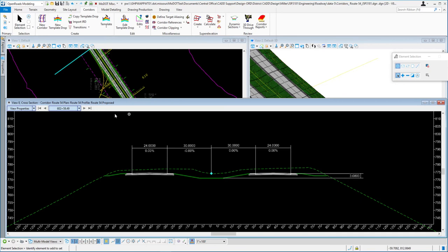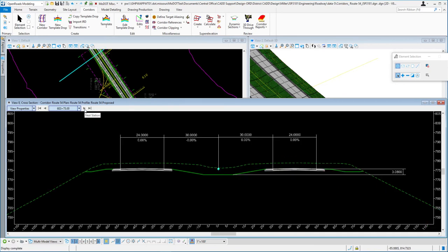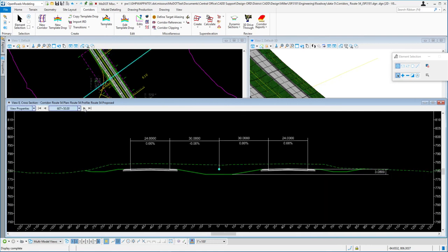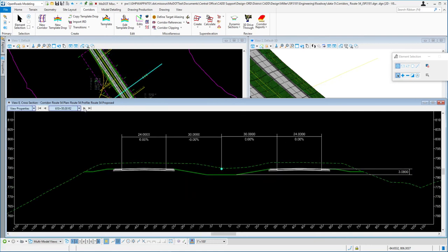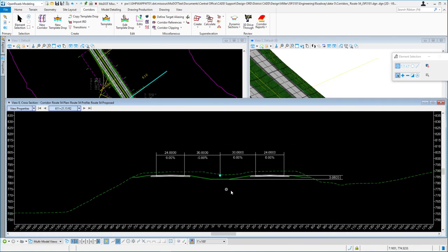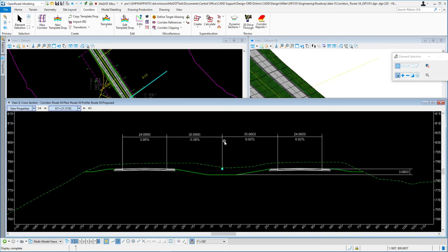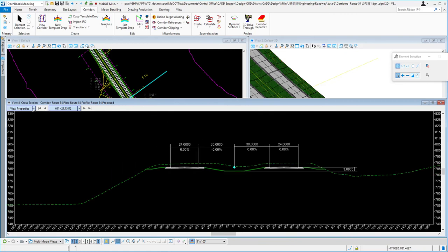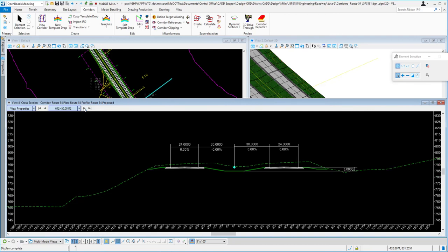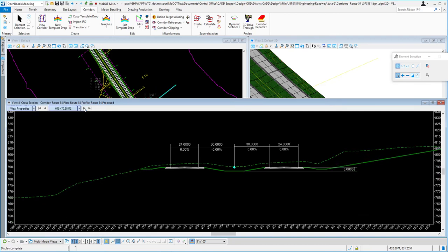And the slick thing about these dimensions is, as we travel using these buttons up here to each station, the next station, you could see that the dimensions go with that. Now if it starts jumping around a lot in different areas, you could set this option over in view properties to center on current offsets, and they will stay. So you can get it to a point where you like it, and you select center on current offsets, just use that pull down. And now when you start navigating through, you'll see that the alignment stays and everything else is rotated around it.